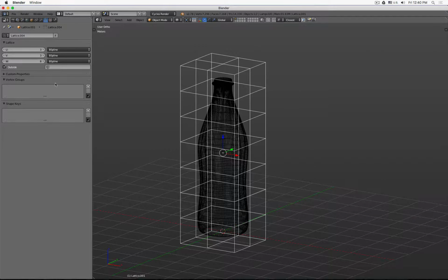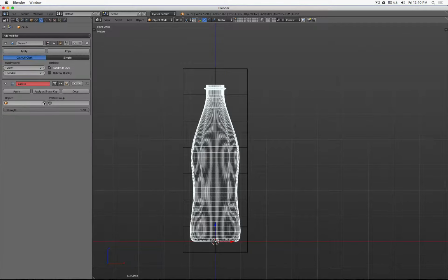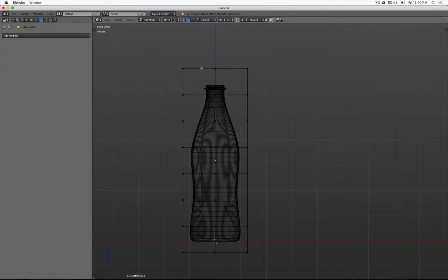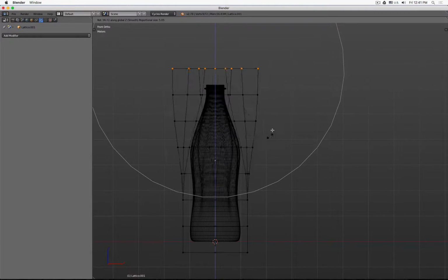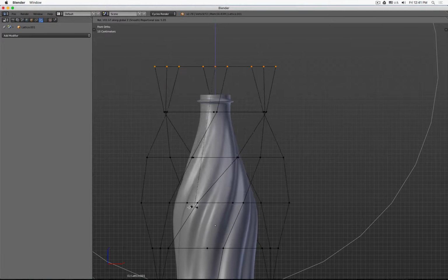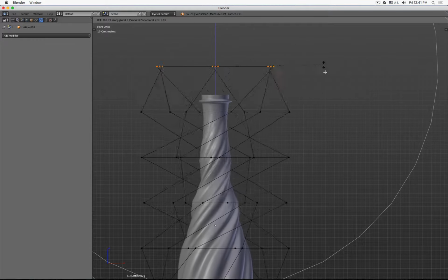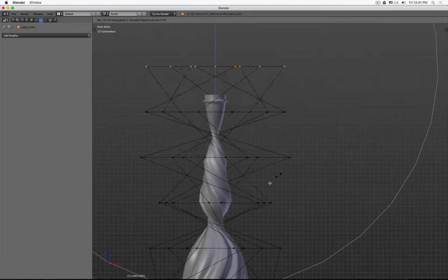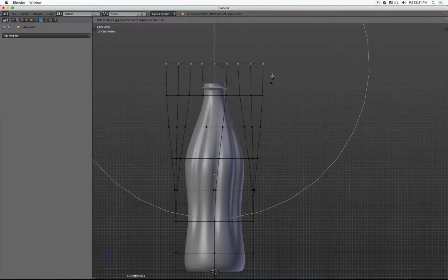And let's say I only want to have the outside points on the body. Okay. Deform with the lattice. There. R and Z. Let's rotate it. Let's pay attention to what's happening. See, it can sometimes get a little bit twisted, and there it's getting smaller and smaller because I'm totally twisting this surface. So we have to be careful about it.